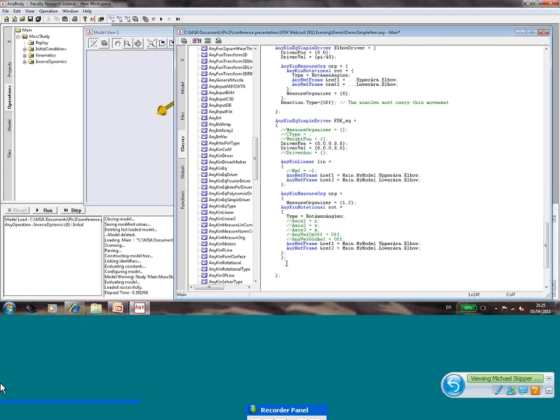Then we need to tell that this kinematic constraint equation is a special one. It is one of these force-dependent kinematic constraint equations. And the way you say that is by specifying C type, and then you write force level. And it needs 5 components because there are 5 components now in our kinematic measure. So you need 5 of these. I'll just copy them. 1, 2, 3, 4, 5.